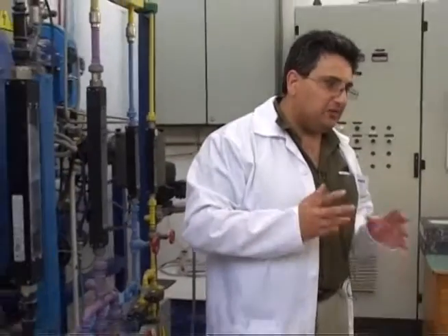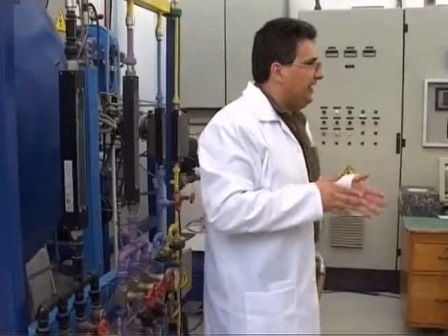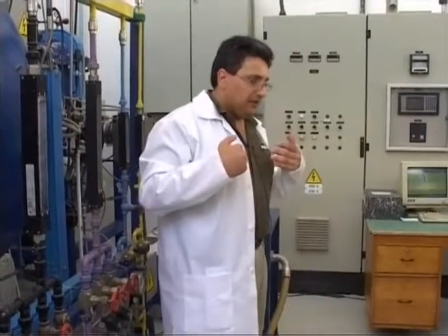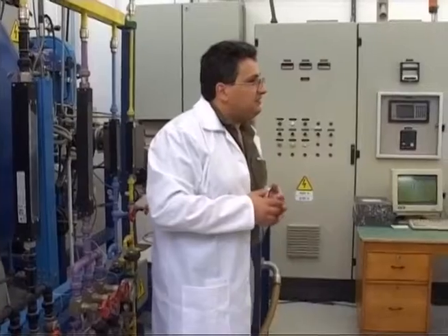This oscillation of electrons generates high intensity plasma, which is known as hollow cathode. The temperature in these regions can increase very rapidly and reaches very high values, thereby melting the component. So in this case, there are two alternatives. Either the cavities are blanked before the process is initiated, or gas nitriding is conducted instead of plasma nitriding.